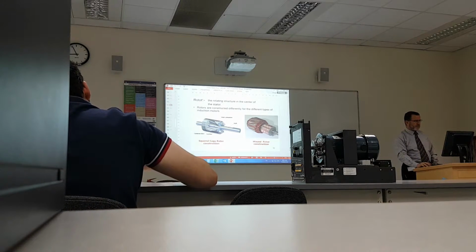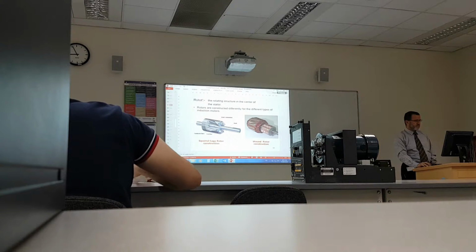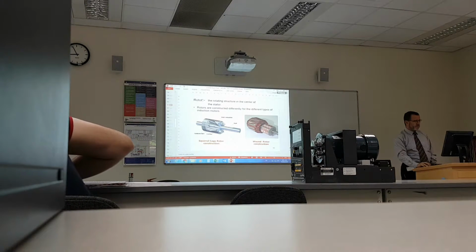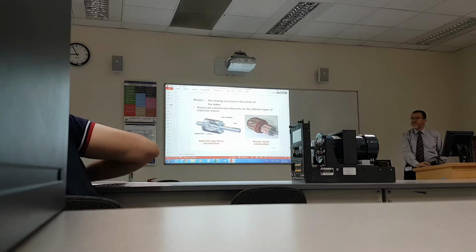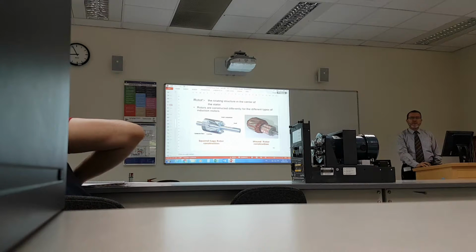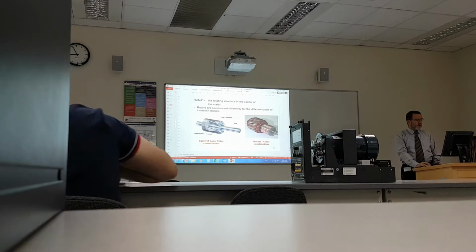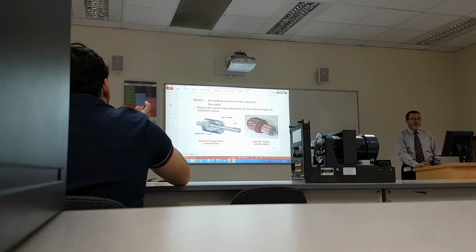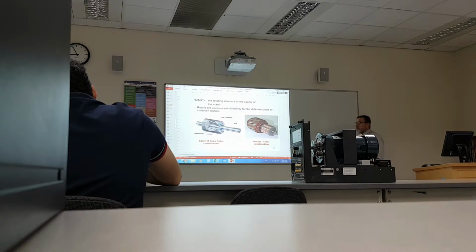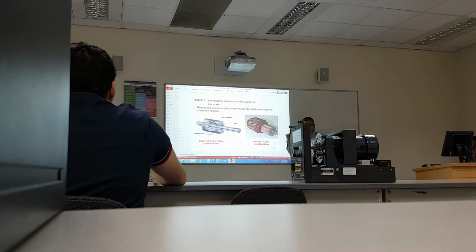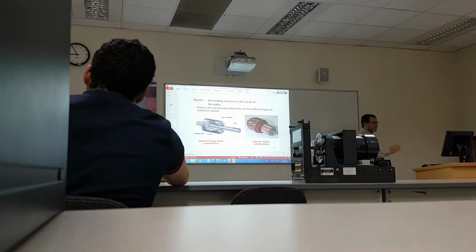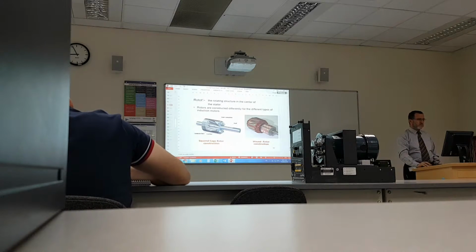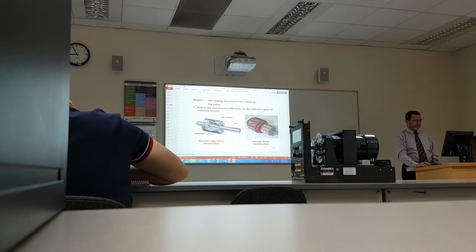Now, I want to give you again some hints. Squirrel cage has high initial current, always between 5 and 10 times. Wound rotor, no. Wound you can control, because you have the external resistors. You can control it. That's the advantage, or how you want to use it.